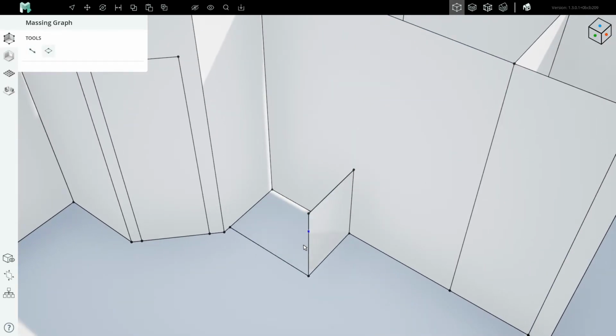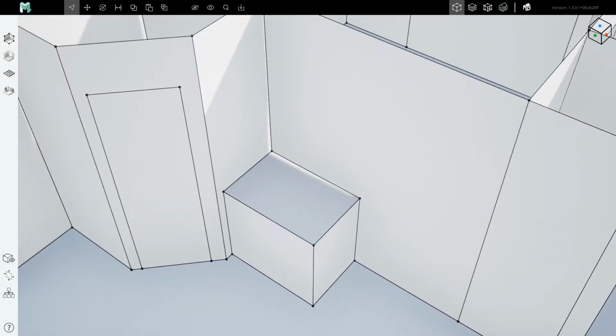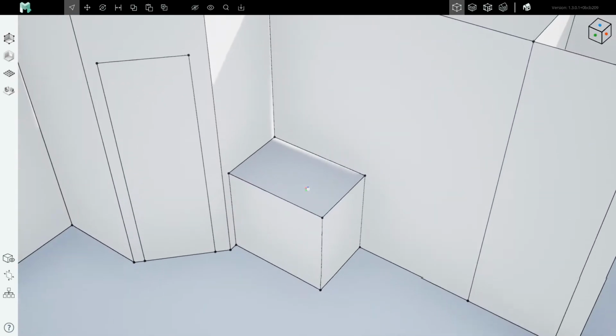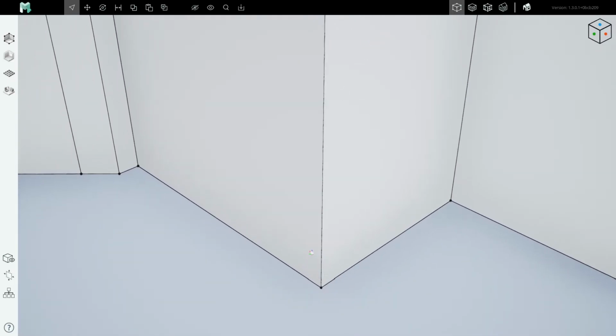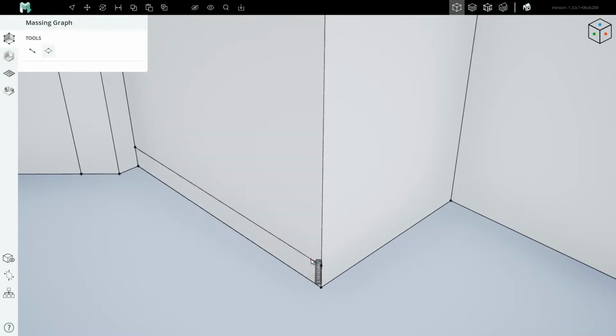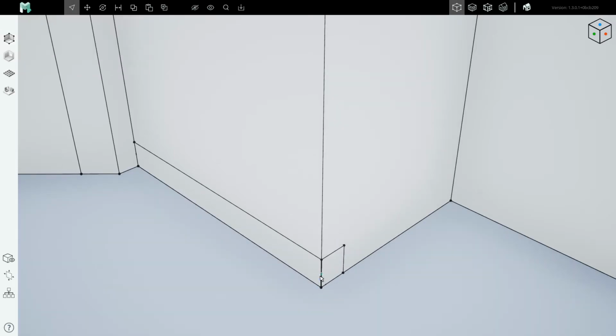We'll use the rectangle tool to complete the rest of this rectangle. I will just bring this one across, and we've successfully carved a prism in the corner of the room. We haven't drawn its toe kick yet, so what I can do there is come up 4 inches and back 4 inches, or how about 3.5 inches, and then come down and snap to here.